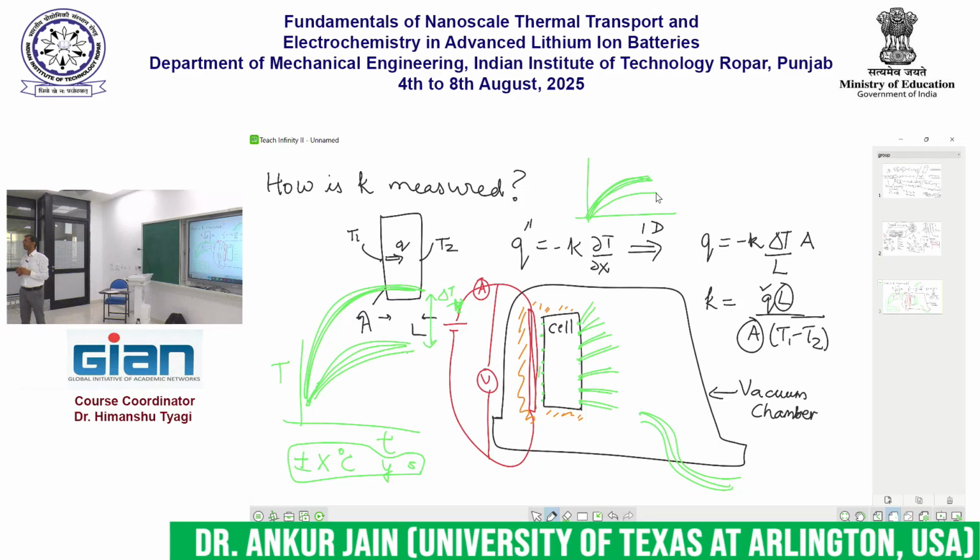to calibrate. Sure, both are very good points. You have to go back and make sure that all of your thermocouples are calibrated. We didn't talk about this, but we should have been doing calibration even before we started this experiment, right? And to your point, we have to make sure that all of these thermocouples are attached correctly, there are no impurities or other problems like that, and so on and so forth. Contacts are perfect. We didn't talk about this as well. See, this is a can of worms. The more you talk about it, the more challenges you foresee in your experimental measurements, right?